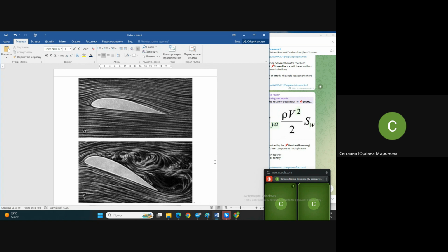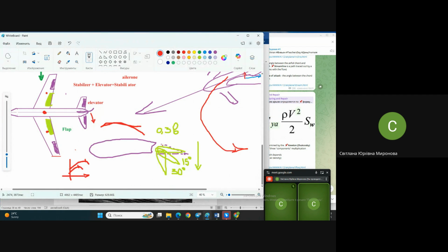So in case you use just a movable flap, just movable like this, hinged and movable, you are limited in these angles. You are not able to move it much. Well, you're able, but it will result in bad consequences. You shouldn't move it much. They are, of course, limited in aircraft structure. You can't move it more than predicted by the designer at all. But you are limited in these values, and it means that you can't increase the force significantly.